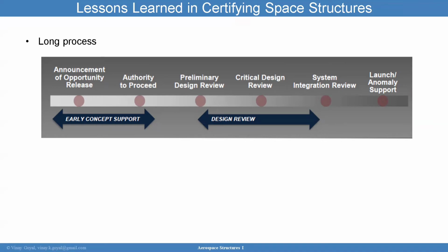Another approach is to just go straight and start manufacturing, start learning right away, which has a lot of up-front cost, and you're going to perhaps have a lot of failures early on. But when something succeeds, you know it works, and you just go for it. And then you try to figure out how my design verification should show that it should be okay. So two approaches. The approach that usually guarantees success is starting from the bottom up: a building block approach, going through reviews and really understanding how everything fits together, because a launch vehicle and spacecraft design are quite complex.